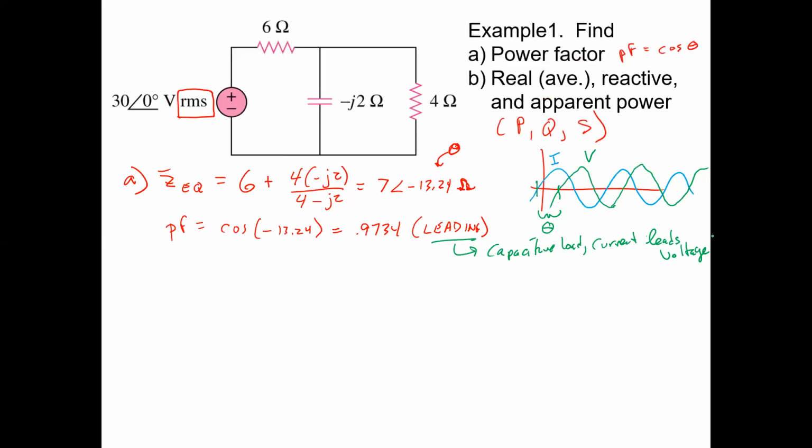Voltage. That's why it's a leading power factor. So when someone says it's a leading power factor, that tells you it's a capacitive load. If it's a lagging power factor, it's the opposite. It's an inductive load.